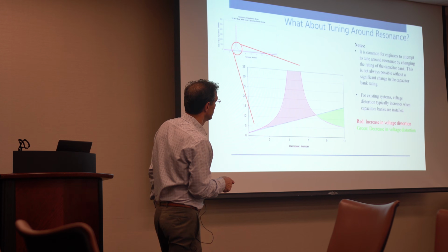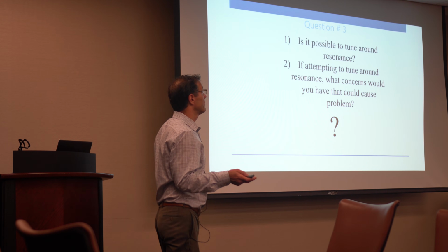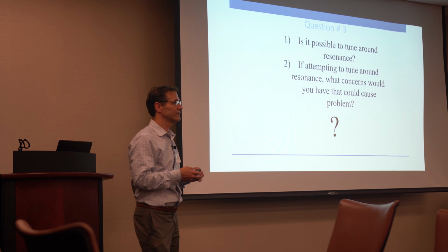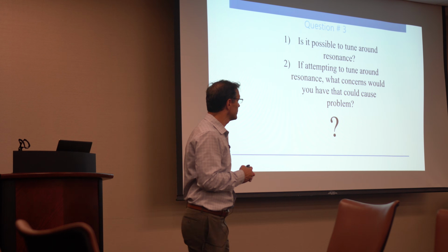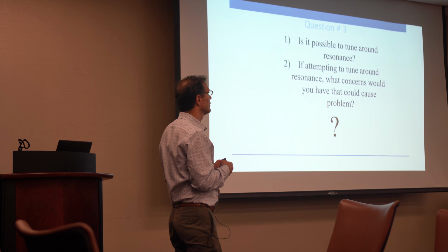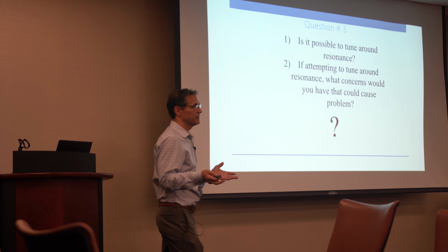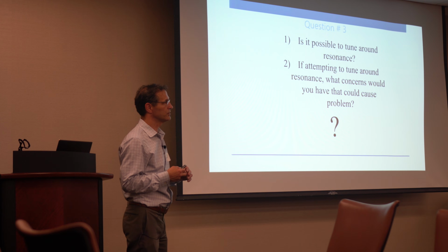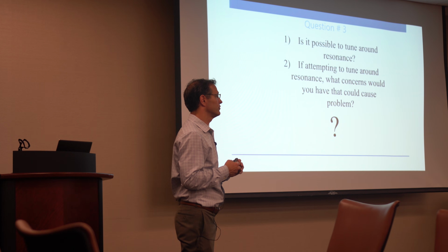So think about that. Third question, is it possible to tune around resonance? I think the answer is no. I think I've talked about that, and hopefully you agree with me on that. If attempting to tune around resonance, what concerns would you have? I think the answer is things are going to move around. Your short circuit impedance will change in the network. So tuning around resonance is not always applicable.